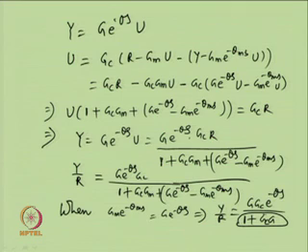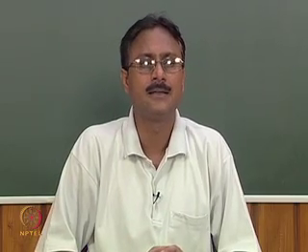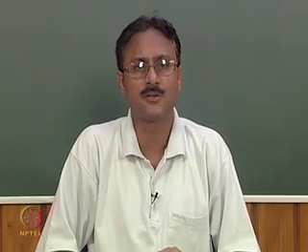The denominator of the closed loop transfer function with respect to the reference input is devoid of any time delay term. Had there been the time delay term in the denominator, as we get from series feedback compensation schemes, then it becomes difficult sometimes to design an efficient controller for many systems.